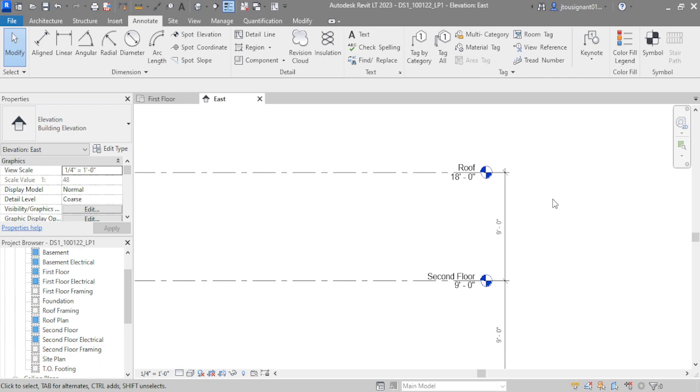And one of the biggest reasons why I wanted to create this type of video where you can see me draw is you're going to notice that when I conceptualize or even lay out existing conditions of an interior floor plan, I almost always draw the walls incorrect quickly and then measure them all up with dimensions and then adjust them afterwards. I just find it a lot easier to get walls and such on paper.